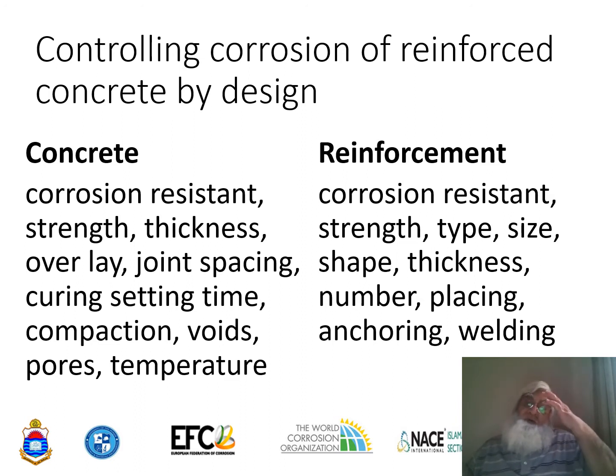For the reinforcement design, you need corrosion resistant materials, which are not based on plain steel, but steel plus additives, or other stainless steel materials mentioned in the previous slides. The strength has to be calculated. The stronger the reinforcement material, the stronger the structure and the less vulnerable to corrosion.